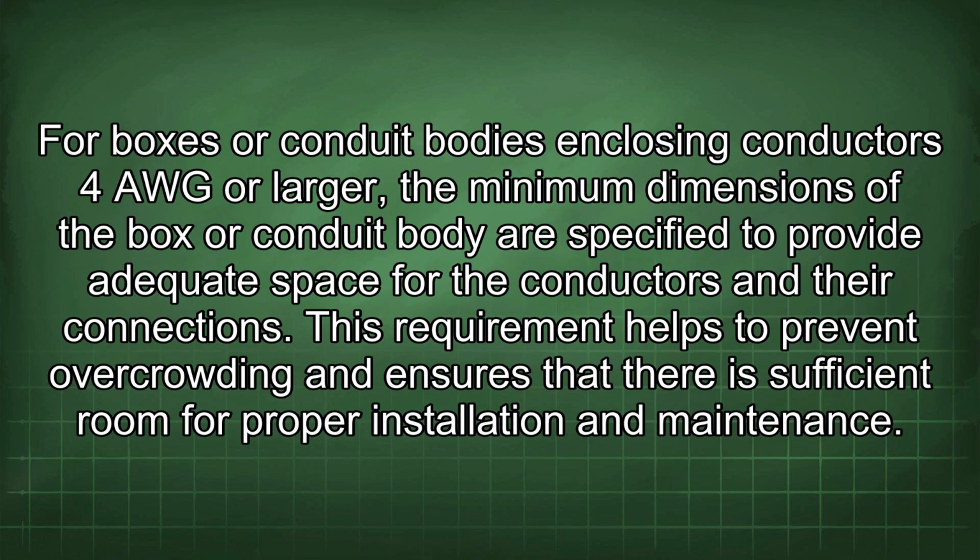For boxes or conduit bodies enclosing conductors 4 AWG or larger, the minimum dimensions of the box or conduit body are specified to provide adequate space for the conductors and their connections. This requirement helps to prevent overcrowding and ensures that there is sufficient room for proper installation and maintenance.